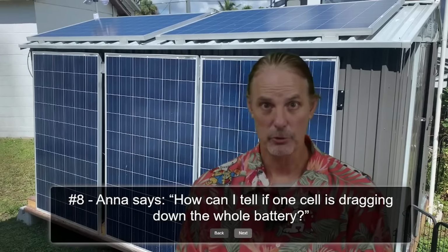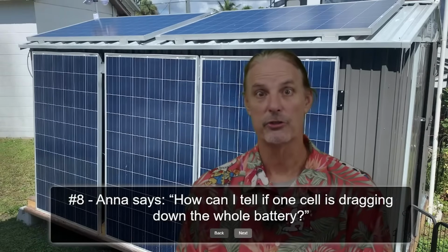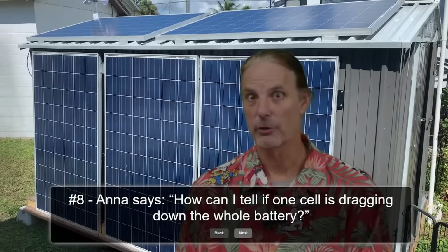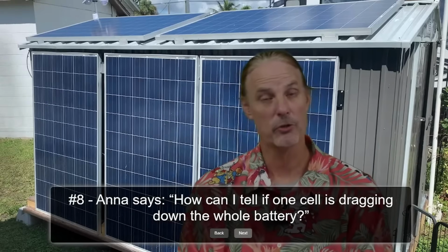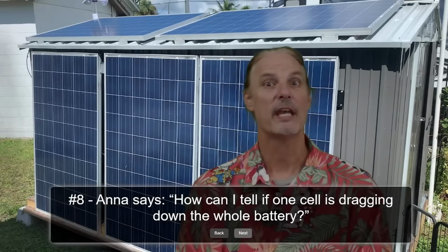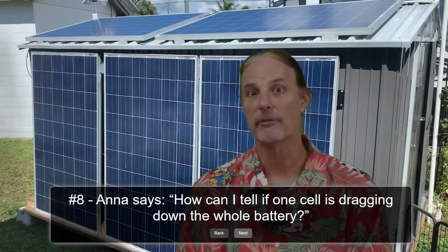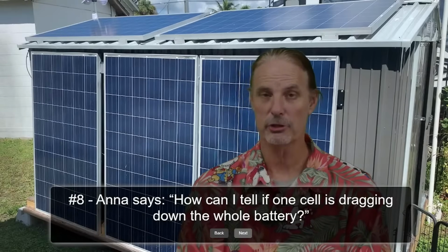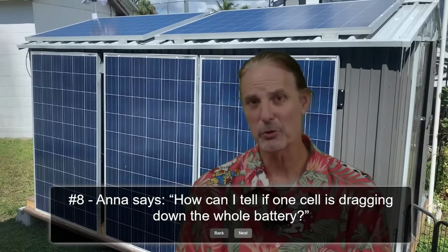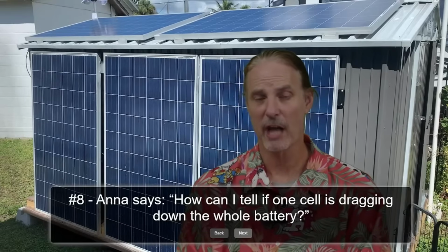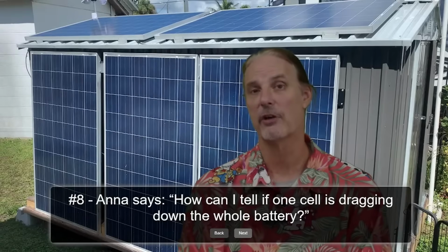And that means that if you do have one that's doing that, signs of that would be that it shows that it's charged before it shuts off, and you see the warning signs of it saying, hey, I'm already charged, when it won't charge all the way. You can't put enough power into it to get it to 100% charge, but you can't bring the voltage up high enough to get it to 100% charge. Those could be signs. If you've got a Bluetooth or something like that where you can get in and see the actual cells themselves, that's your best bet, is to look at the actual cells and see if you have one that's running behind.